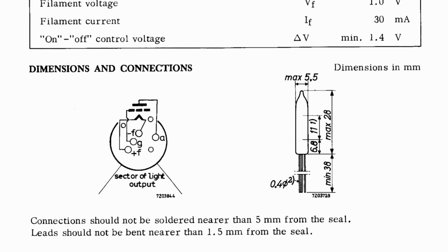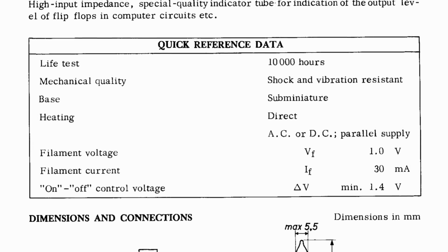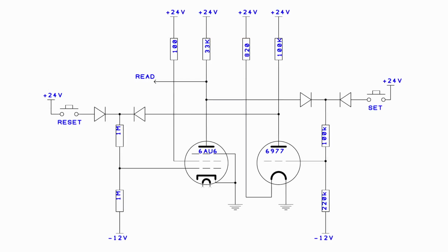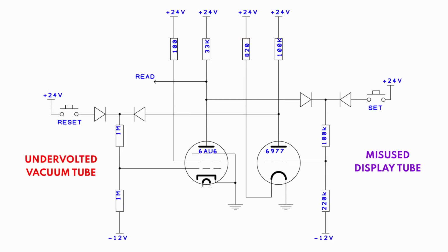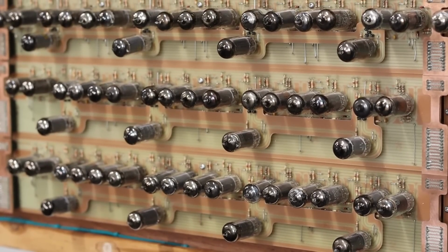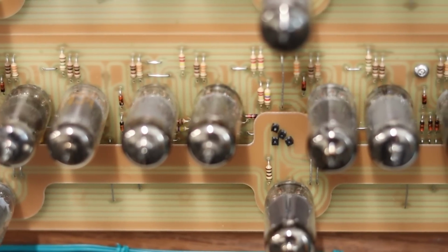The VFD is actually a triode, but it's not meant to be doing any actual work. It's a vacuum fluorescent display. It's meant to only display stuff. So using it as half of a flip-flop means that if that balance between my unhappy 6AU6 and my misused VFD gets out of whack, the flop may not flip and the flip may not flop. It's just not great. However, these daughter boards here plug into the through holes for the VFDs, which have now been removed, and they actually make more effective use of the available space.